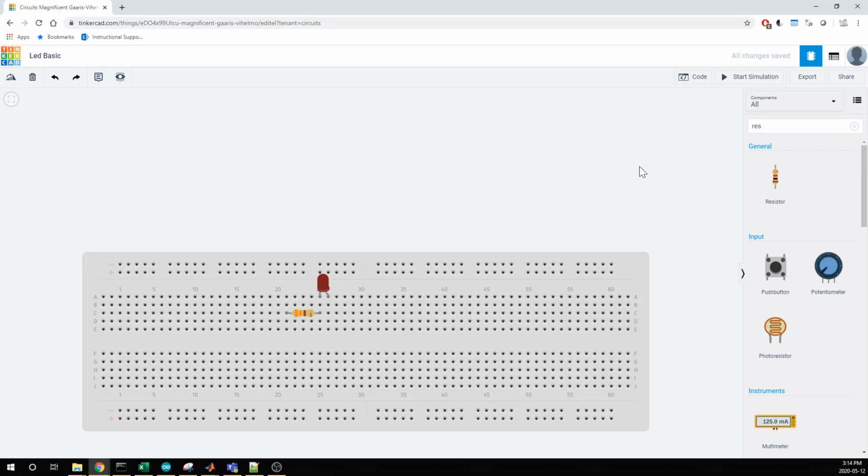So the next thing I need to do is connect it to power. And again, I want to stay away from power for as long as I can. I don't want to power my circuit until I'm really ready and I'm really sure. And that's where I'm going to use the breadboard's rails. So what I'm going to do is I'll take from this hole here, which is connected to the longer leg of the LED, and you'll notice over here on this column, this is called a rail actually, I have a plus, and this is where I'm going to be putting the positive end of my voltage source. So I'm going to click here to get a wire coming in. I'm going to drag to another hole in the rail I want, and I'm going to click on that, and it will make the connection.